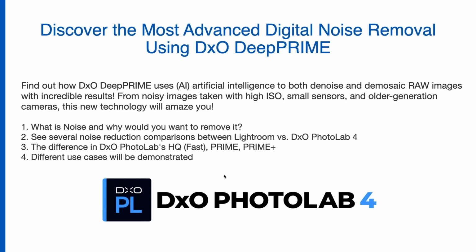Whenever you vary from that, whenever you increase the ISO or even decrease the ISO, you are going off of the native sensitivity of the sensor and of those photosites. And the process of changing that native sensitivity is called gain. You are gaining up or gaining down the sensitivity of the sensor. That process of gaining it up or down is effectively an amplifier.